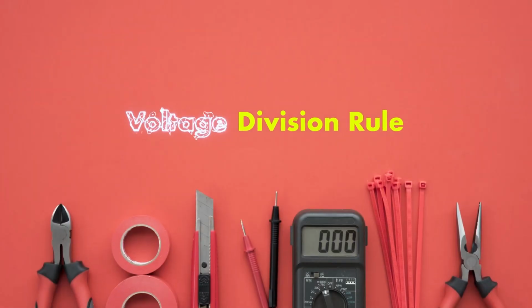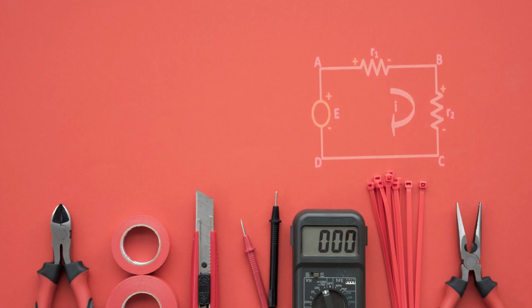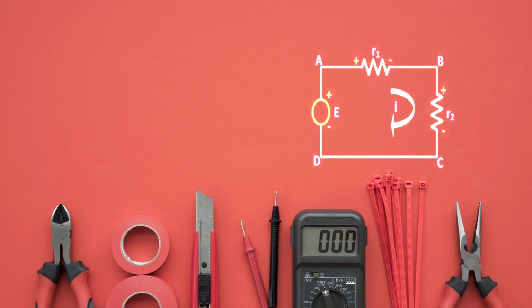Now we have to understand the voltage division rule. Here you can see that between terminal A and B there is one source, that is E, and between terminal A and B there is a resistance R1, between terminal B and C another resistance R2, and all these three elements are connected in series. Now you have to find the voltage across terminal AB and the voltage across terminal BC. As per the voltage division rule, we can easily calculate the voltage VAB and the voltage across terminal BC, that is VBC.